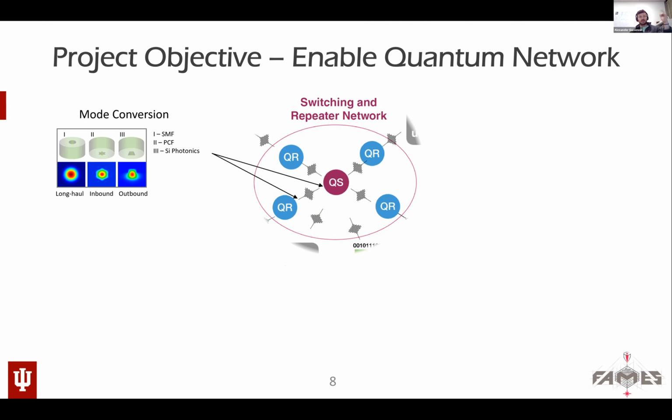On the inbound platform, you might have, for instance, a silicon photonics chip. In a silicon photonics chip, you have a rib waveguide, which has rectangular symmetry with high refractive index on the side of a wafer, so it draws the electromagnetic radiation towards the high refractive index. Effectively, you will have a trapezoidal symmetry of a mode.